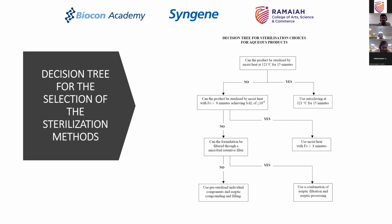So this is a level of aseptic processing and aseptic filtration, but is not a full-fledged aseptic processing from start to finish. It is limited to a certain portion of your process itself. The last answer, no, I can't filter it through a microbial retentive filter. What are the situations here? Suspensions. I can't filter a suspension through a retentive filter, because if I do that, then the particles which are suspended in the formulation, which are critical for the injection themselves, get filtered out, because they are larger than the microbe itself. So the microbial filter will keep the particles apart also. So I can't filter it.